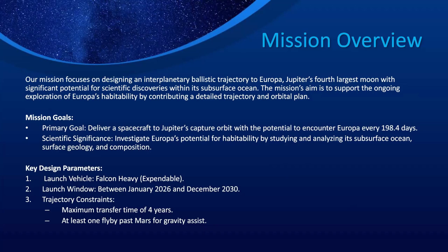A few of the key design parameters used for this trajectory. Our launch vehicle, of course, is the Falcon Heavy expendable. Our launch window is between January 2026 and December 2030. And our trajectory constraints in designing this trajectory, the first was a maximum transfer time of 4 years and at least one flyby past Mars for a gravity assist.